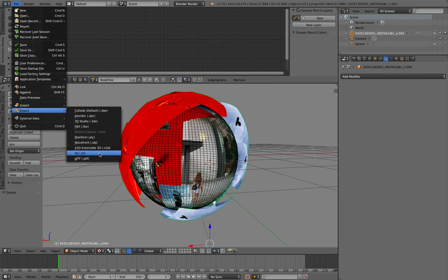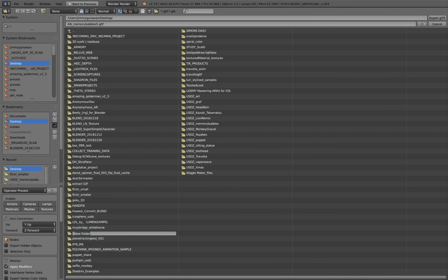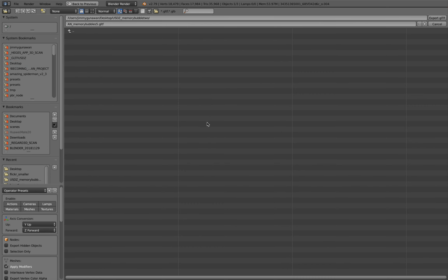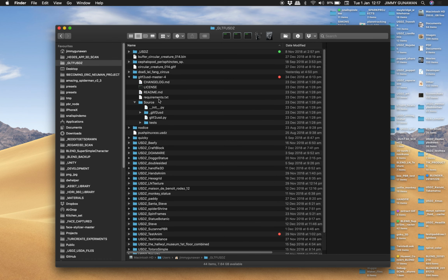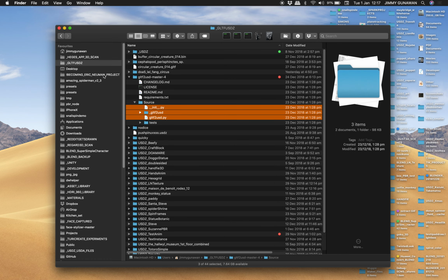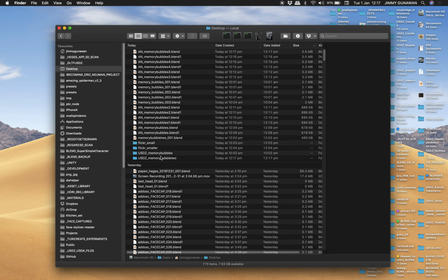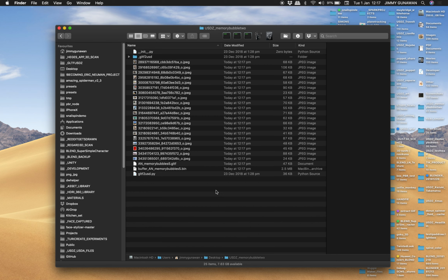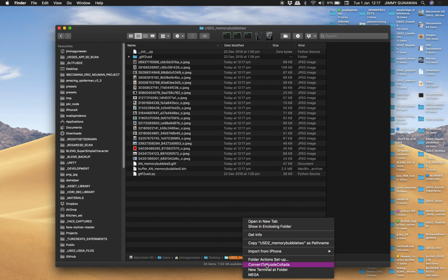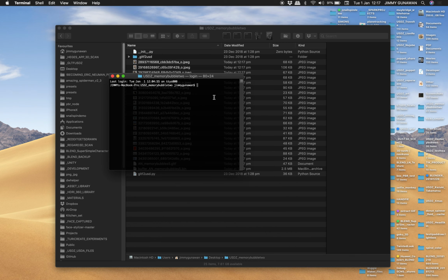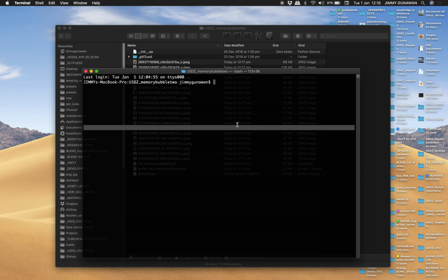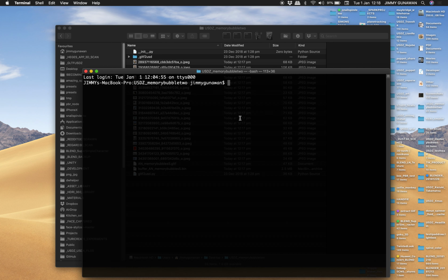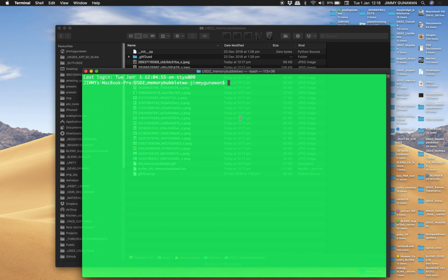Export. GLTF. Final. And USDZ. Memory bubble 2. USDZ memory bubble 2, save GLTF. It's gonna save with texture back to my magic script. Thanks to Casey Colley for this script. It's really, really handy. For now, at least, if you have GLTF, you can create USDZ pretty much. For simple animations, it doesn't have fancy stuff like blend shape because of the limitation of USDZ at the moment. But anyhow, we are done.